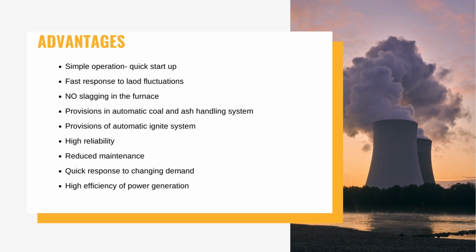High efficiency of power generation. By operating the fluidized bed at elevated pressure, it can be used to generate hot pressurized gases to power a gas turbine. This can be combined with a conventional steam turbine to improve the efficiency of electricity generation and give a potential fuel savings of at least 4%.